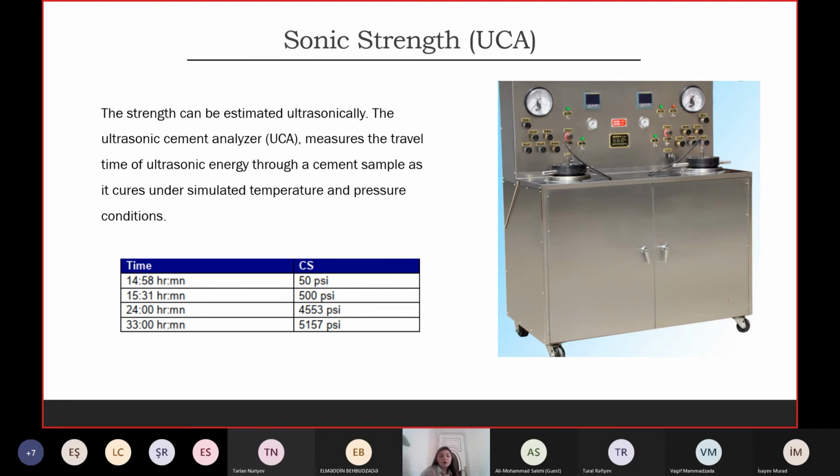Probably you have seen a whipstock. When you want to do a sidetrack, you are drilling, and you need to have a plug here which should guide you to another hole, not the same hole you are drilling, right? That's why it should be very hard. It should be stronger than your formation, because it should guide you to the formation, not down through the plug.